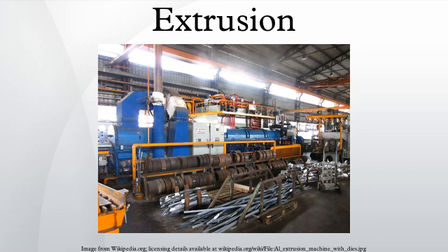Surface lines, when there are lines visible on the surface of the extruded profile. This depends heavily on the quality of the die production and how well the die is maintained, as some residues of the material extruded can stick to the die surface and produce the embossed lines.